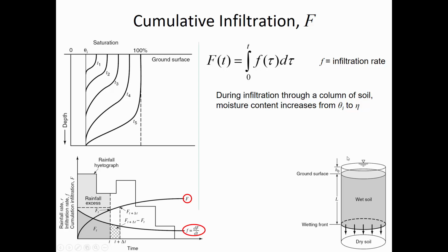And essentially what we're seeing is a column of water penetrating down through the soil, and there's this immediate increase from the initial moisture condition to full saturation, where L is going to be, over time, the length that that water column penetrates down into the soil.